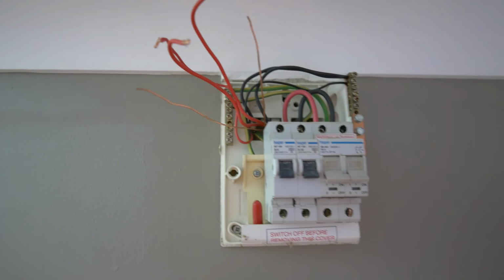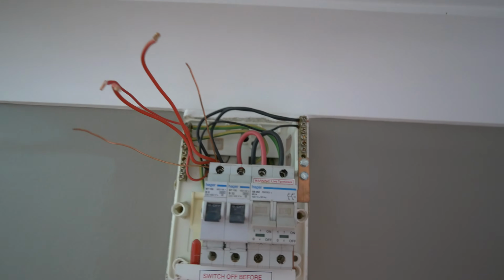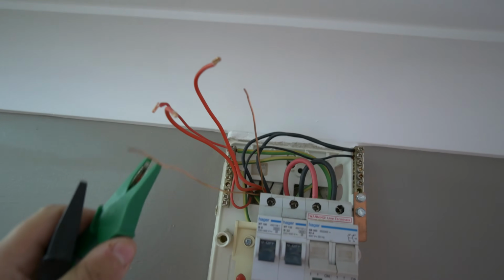And then the first thing we need to do with the ring final, if I get these croc clips apart, just bear with me. So the first thing I need to do is get some end-to-end resistance readings on the line, CPC and neutral of this ring final circuit. So we'll do the CPCs first, and of course the installation electricians had put them in the same sleeving just to make things lots of fun. So you can see they're not touching in the back there, to make sure you do keep them separate.